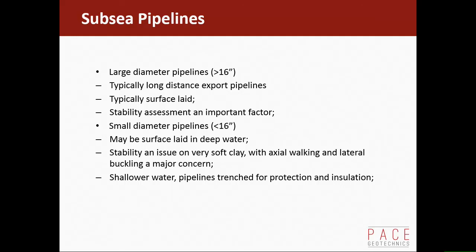I've already said all of that, except for the last bit, which is that in deeper water we do lay the pipelines on the seabed. And if you remember last time when we talked about pipelines or seabed geology, in deeper water you tend to have very soft clays. And then you get a phenomenon called axial walking, lateral buckling, which I won't describe the process of.